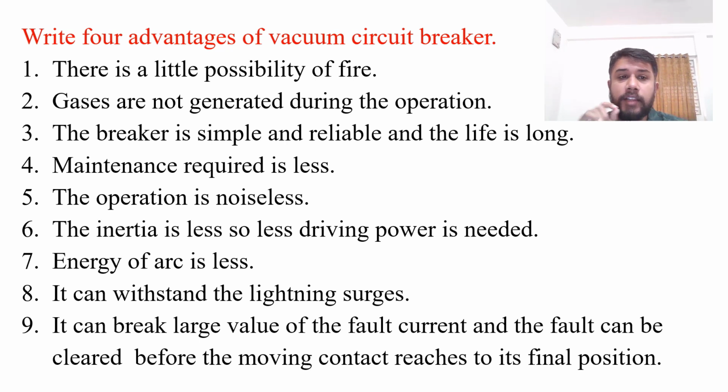So first is, there is little possibility of fire as the vacuum is the absence of air. So the possibility of fire is very less. Gases are not generated during this operation. The breaker is very simple, reliable and robust in construction. So the life is very long. Maintenance required for this type of breaker is very less. The operation is noiseless, means quiet operation.